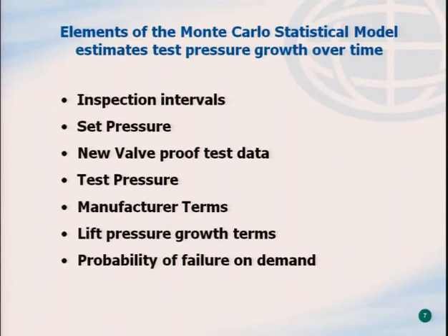Elements of the Monte Carlo simulation. I mentioned that we do model the new valve database, valves that have not been aged. And once they're placed in service, they have various inspection intervals, different set pressures. And there's also different manufacturers. And the main purpose of this is I want to estimate the probability of failure on demand.